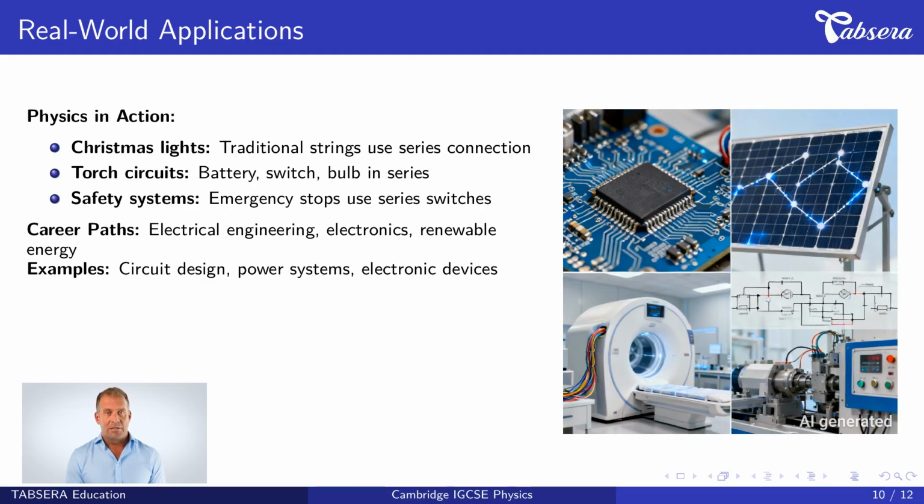In torch circuits, the battery, switch, and bulb connect in series, creating a simple but effective lighting device. The same current flows through all components. In safety systems, emergency stops use series switches, where any switch can break the circuit completely, ensuring immediate shutdown. These applications show why understanding series circuits matters.